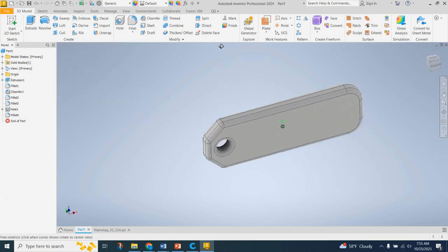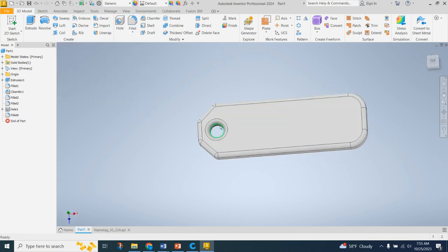And I'm just going to go ahead and let it match that outer fillet. Click OK. All right, so that's going to wear much nicer. It's going to be easier on the chain, and this will last longer. It won't just chip away at that hard corner and wear away in your pocket.